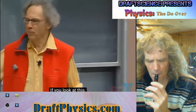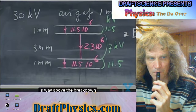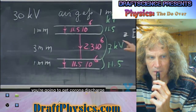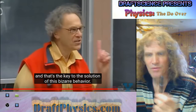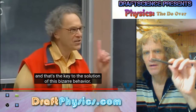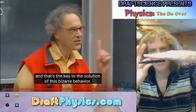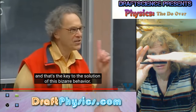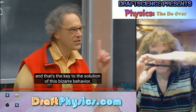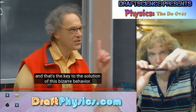If you look at this, it cannot be, because a field of 11.5 times 10 to the 6 is way above the breakdown electric field. And so what's going to happen? You're going to get corona discharge from the conductor to the glass. And so what you're doing is you're spraying charge on the glass. But it's the wrong kind of charge, because the glass was negative. Let's say the copper is positive, the glass goes negative because the two are in association. So that's the theory. And now he's saying, no, what's really happening is the positive charge is spraying onto the glass, and now this glass is becoming positively charged.